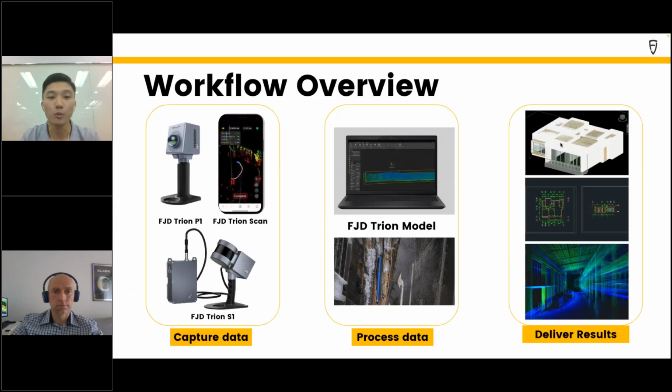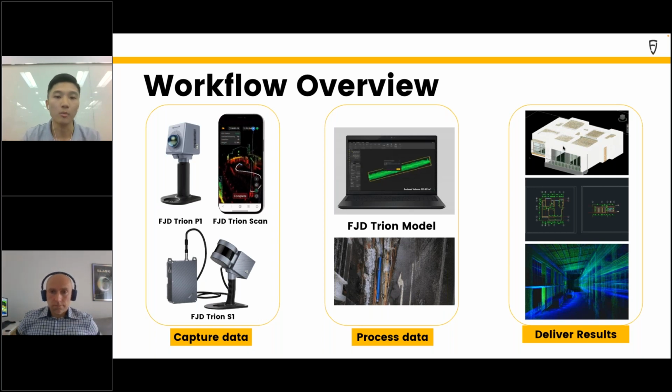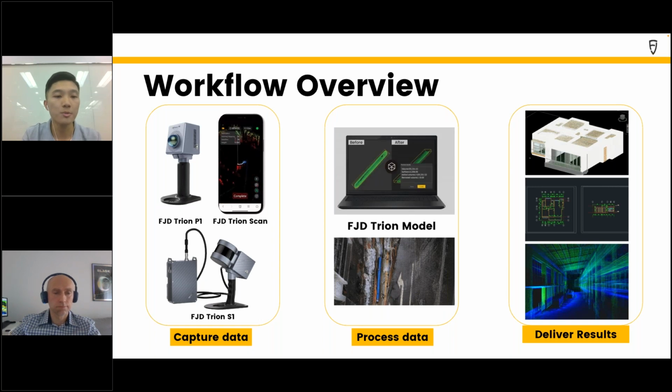And we will have the workflow overview here to let you guys know a little bit more about how we walk through all this scanning and processing data, and eventually the outcome. We have the data processed for other applications. On the left-hand side, you can see we will either use P1 or S1 to capture the data first, while we are monitoring the point cloud in real time. You can monitor it on our phones or any device that's connected to the scanner.